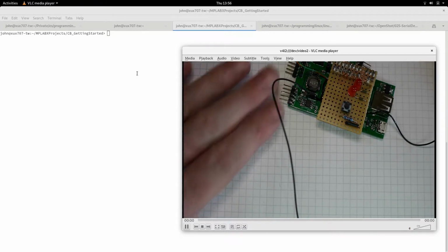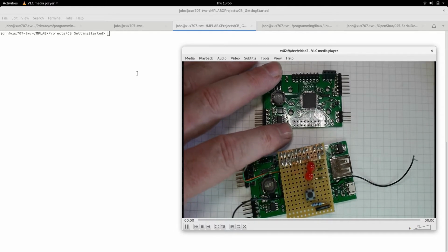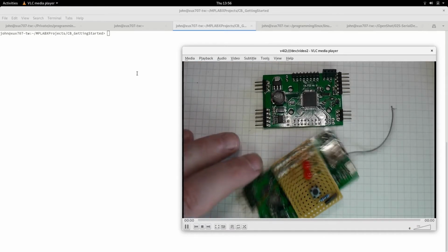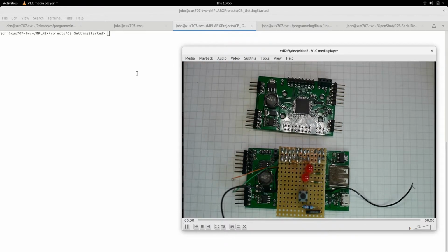So why would you have just gone with serial and not just gone straight to Bluetooth? Partly it's simplicity. Serial interface is just so easy and cheap, both financially, because ultimately all you're doing is switching a GPIO pin on and off, and in terms of the actual silicon resources. The microcontroller power that's needed to do that is trivial. So it's very easy to put onto a product.